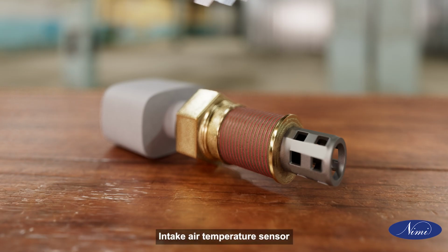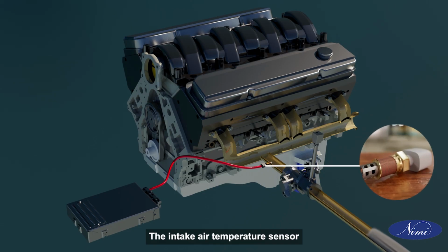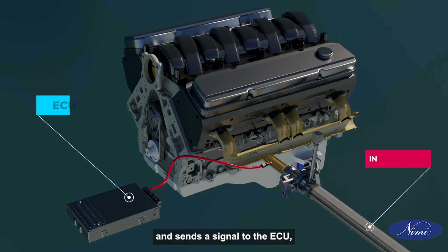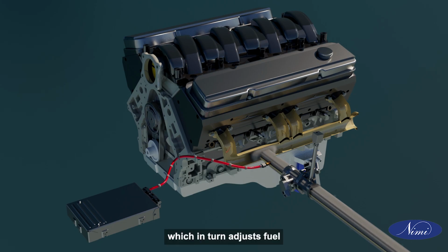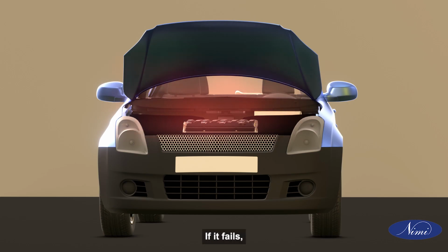Intake air temperature sensor. The intake air temperature sensor senses the temperature of the incoming air and sends a signal to the ECU, which in turn adjusts fuel and idle speed according to temperature. If it fails, your car might overheat or stall when idling.